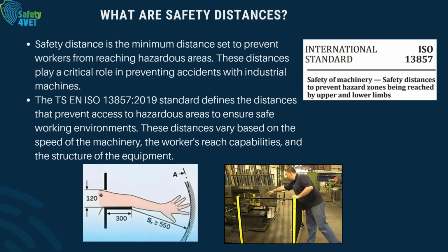Designing machines safely is a vital step in preventing workplace accidents. It is mandatory to conduct risk assessments in the machine design process to identify potential hazards and take measures to reduce these risks. International standards, particularly the ISO 12100, guide this process. Machines are complex systems composed of parts and components assembled to perform a specific function. These systems must operate safely, be easy to use and maintain, and be equipped with safety measures that protect users from hazards.